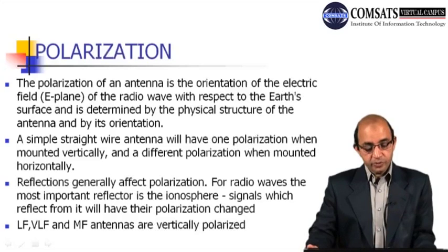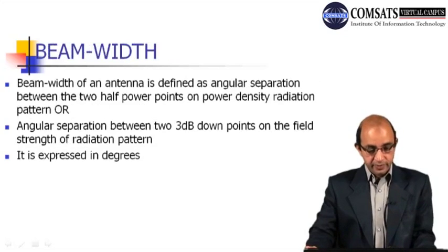For radio waves, the most important reflector is the ionosphere. So as we know, the signals which reflect from it will have their polarization changed. So low frequency, very low frequency and medium frequency antennas are vertically polarized.